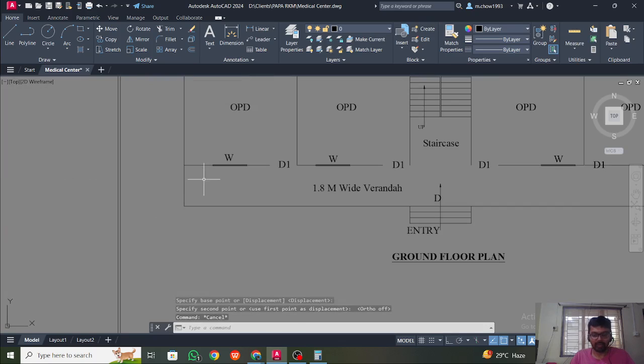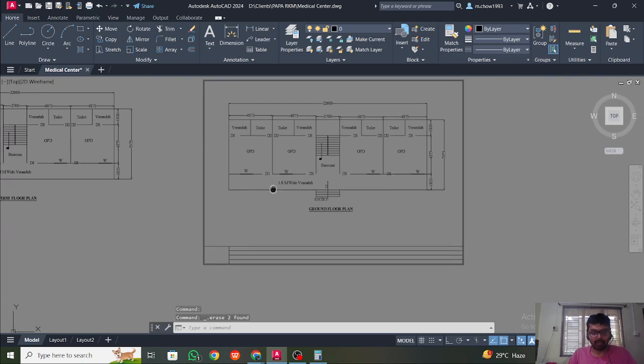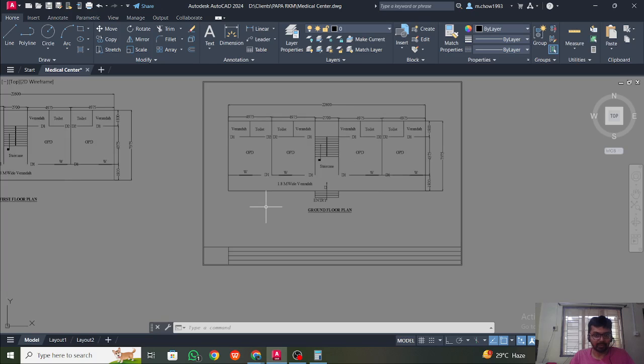So if you just want to add the walls, simply if you have a centerline diagram, so if wall is 250 mm wall, so just 125 on both sides, offset like this, offset like this. I can easily add the walls here. So I'm not going to add the walls here, there's the requirement, only the conceptual centerline plan here. This is the thing. Hope I haven't missed anything here.